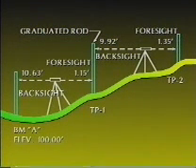The rod is then moved forward, if possible, an equal distance to the backside and placed on an intermediate turning point. The level is turned, and a reading is taken again on the rod at the foresight turning point. This foresight reading is then subtracted from the HI of the instrument to give the elevation of the turning point. In our example, this would be 110.63 feet minus 1.15 feet equals an elevation of 109.48 feet for the new point. The level is then moved ahead and set up at some convenient point.